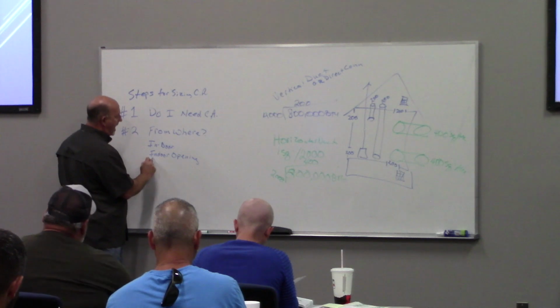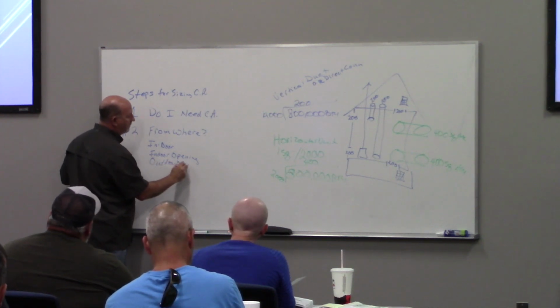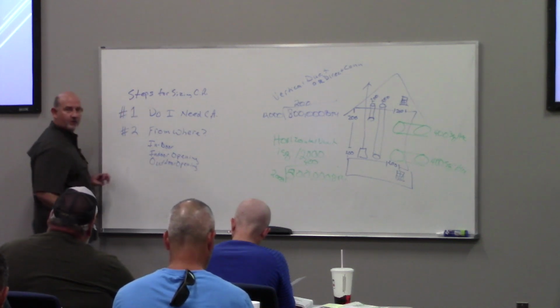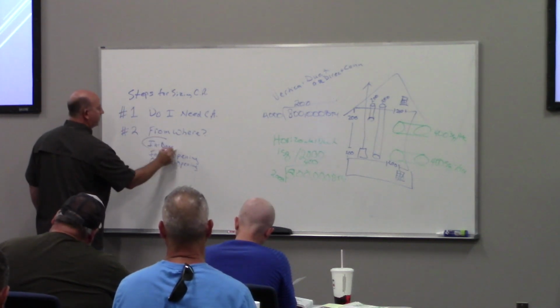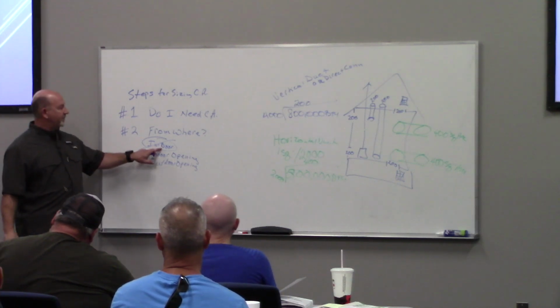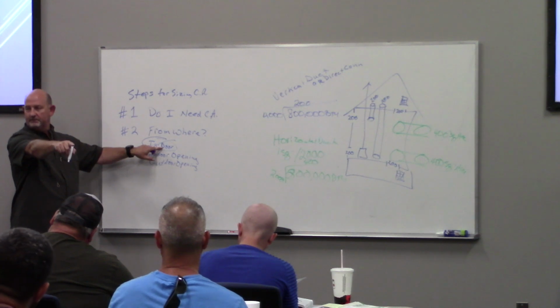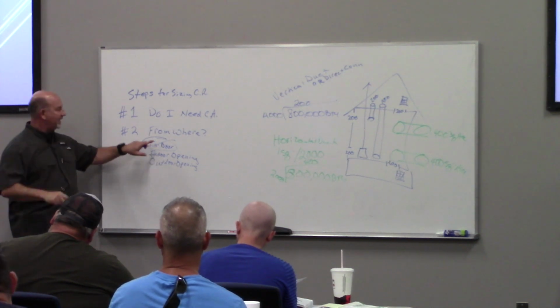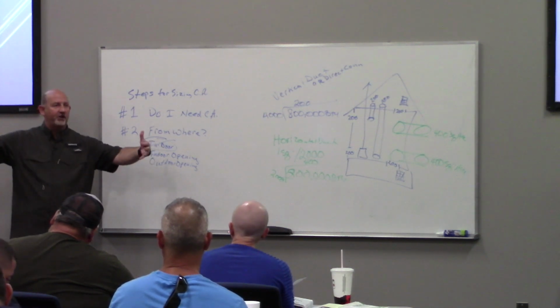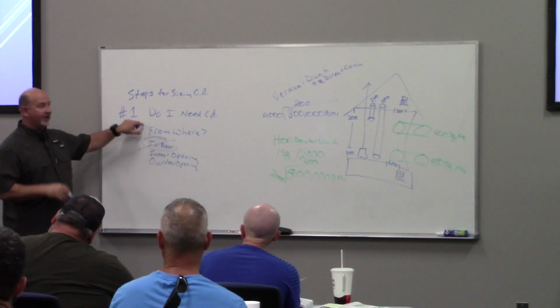Can I get it from an outdoor opening? Now, everybody look up here. Watch this. I'm going to mark that one out. The reason I'm going to mark that out is because if the room was big enough, I would have never gotten to step 2. Make sense? If I'm going to get it from right here indoors, right here in this room, then I would have never gone to step 2. Room's big enough, you're done.